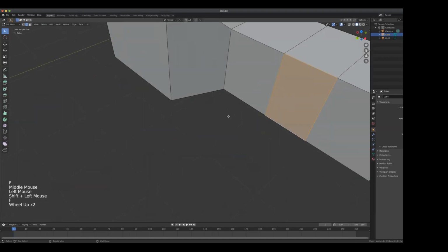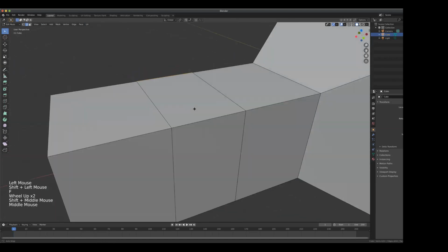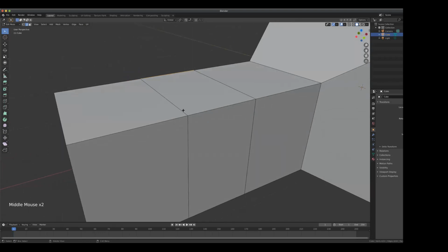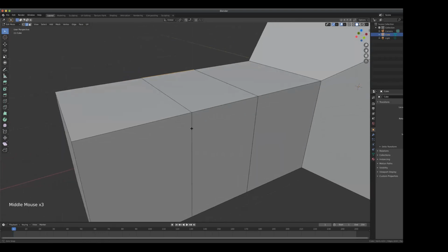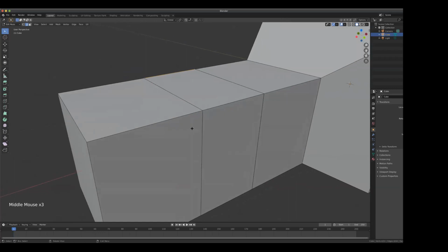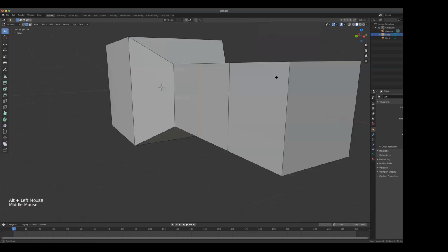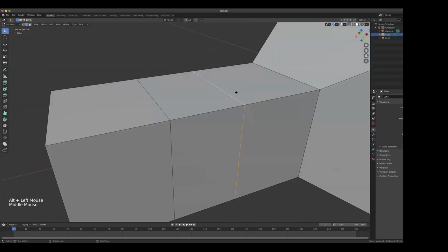The difference is we connected this one, but it generated a line right here, as opposed to when we were merging them, it just kind of jumps into position. All right. So, but there's still ways to make it look like the other one where we jump it here. So I'm going to select this edge, and I'm going to select all of them. If you want to select all of them, simply hold down Option or Alt and click, and it just does a round selection. And then press X, and simply dissolve edges.